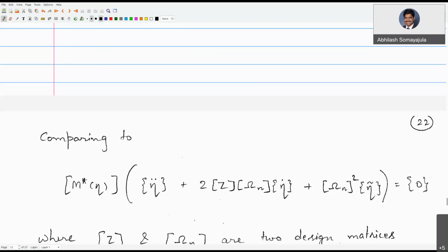There one answer I can give you in that case, Aditya, is you may look at sliding mode control or things like that. There you're saying that whatever the dynamics of the system, I don't care, I'm going to force it to follow certain system dynamics which I want. And then I'm applying a whole load of control computation in order to make sure that my system follows the dynamics which I intended. Again, there you have to prove stability from the Lyapunov perspective, but then it's no longer PID control.